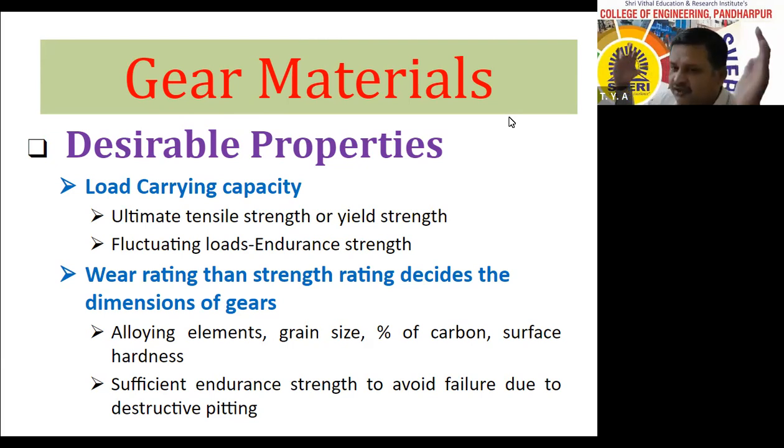Bigger gears, always remember, are manufactured using cast iron. And then the outer surface layer is manufactured using alloy steels, because alloy steels are costlier than cast iron. Alloy steel gears are generally used in two-wheelers and four-wheelers, where we require an exact speed ratio. And alloy steel means what? They have good wear resistance, so the reliability of those gears is more.